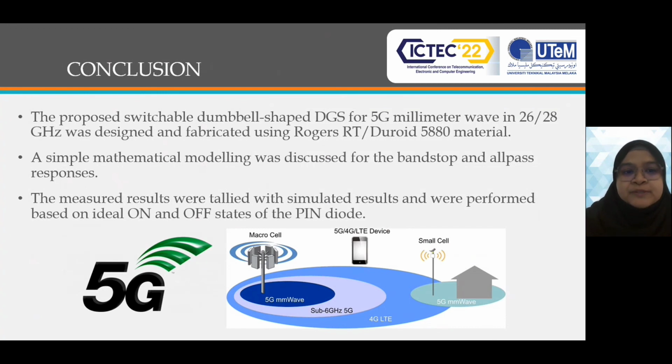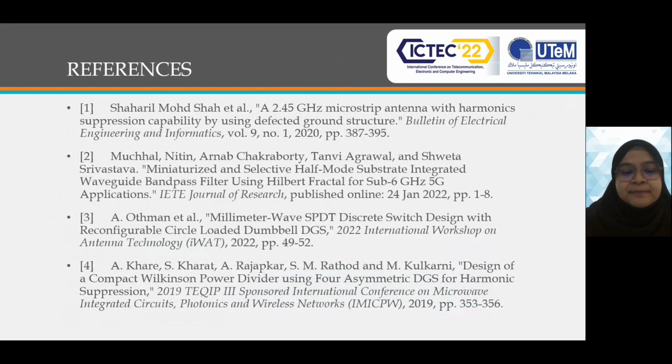As a conclusion, the proposed switchable dumbbell-shaped DGS for 5G millimeter wave in 26-28 GHz was designed and fabricated using Rogers RT Duroid 5880 material. A simple mathematical modeling was discussed for the bandstop and all-pass responses. The measured results were tallied with the simulated results and were performed based on the ideal on and off states of the pin diode. Lastly, these are all the references that are used in this research.